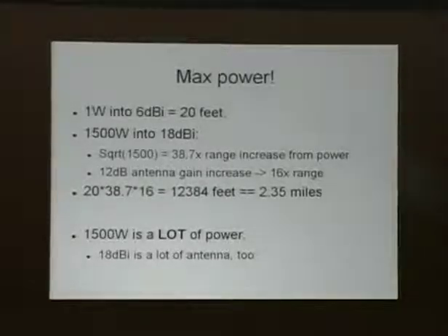True, okay. 1,500 watts is a huge amount of power. That's terrifying power levels at 900 megahertz. That's instant sterility. Likewise, 18 dBi is kind of a lot of antenna. That's pretty much pushing the limit of what you can buy off the shelf.